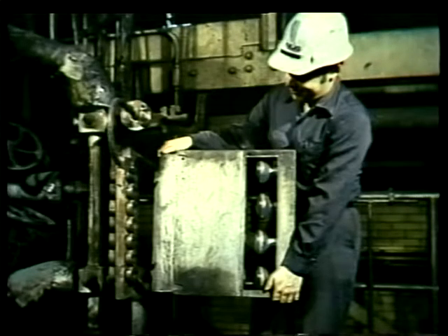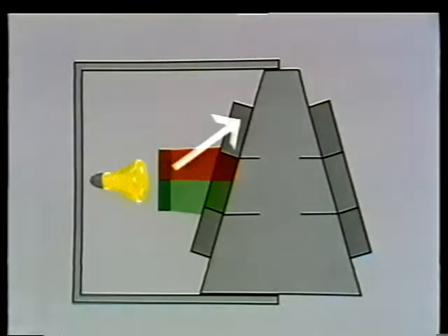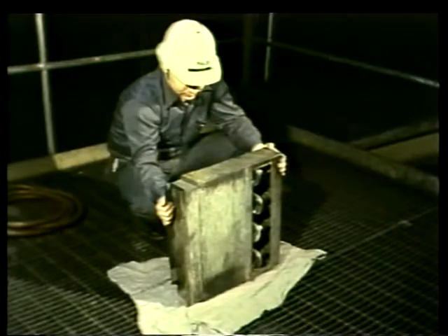After the gauge drains properly, remove the illuminator. The illuminator has color screens that make the gauge ports look red or green. If the illuminator or its color screens are dirty, clean them up. After you clean the color screens, put them back in the illuminator. The red screens should be towards the thin side of the gauge body, and the green one towards the thick side. Then set the illuminator down where it won't be damaged. Do all your work in a clean area.